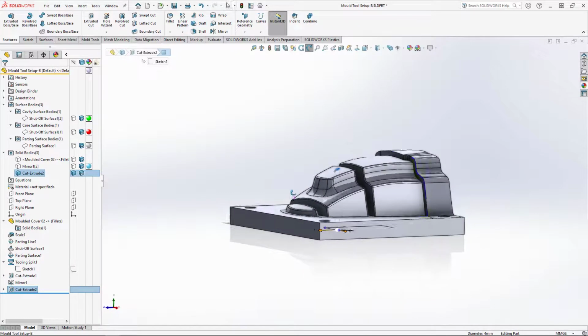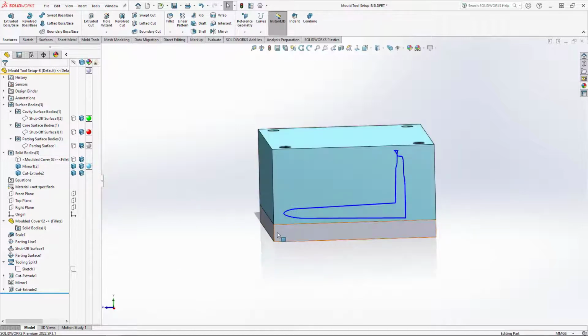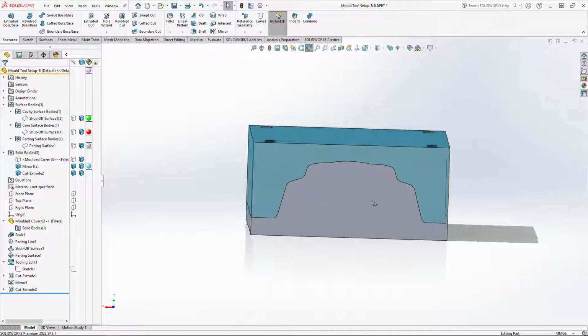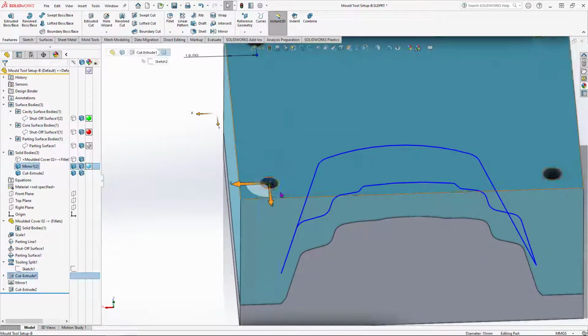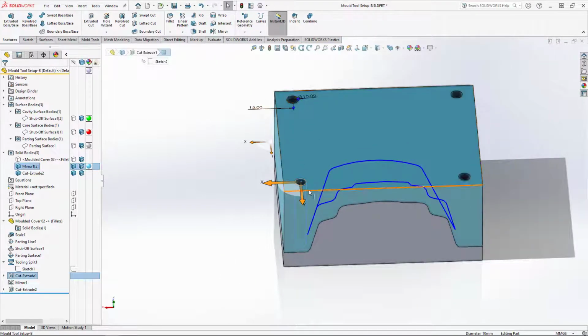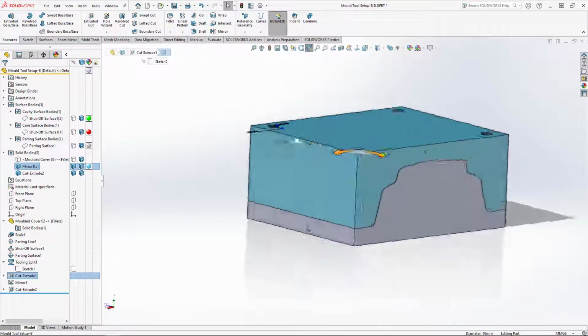Another one, which as I spoke about earlier, are cooling channels through the mold. So in order to add cooling channels to this mold design, maybe we would need some more material down at the bottom here, maybe some more at the top. And the cooling channels could just be holes that pass through either from this face all the way through, or from maybe the back face all the way through. Obviously you would have to ensure that they do not interfere with the clamping holes, because otherwise you would get water pouring out of the clamping locations.